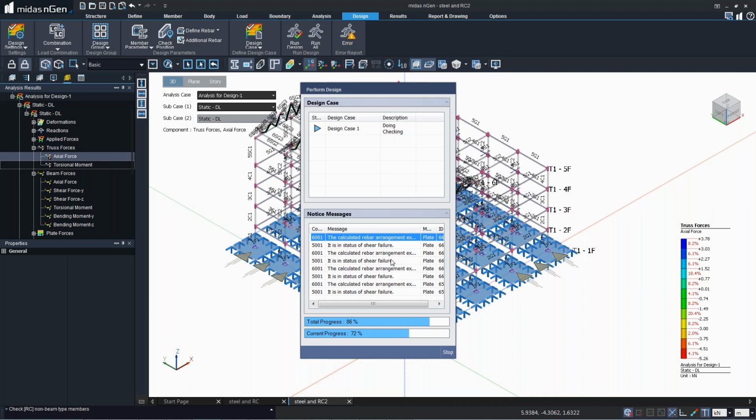Another thing, when we are using plate elements and we do not want to transfer the load from any edge, then we can use plate end release. That's the command. Yesterday in the water tank session, we had seen how to use that particular command.